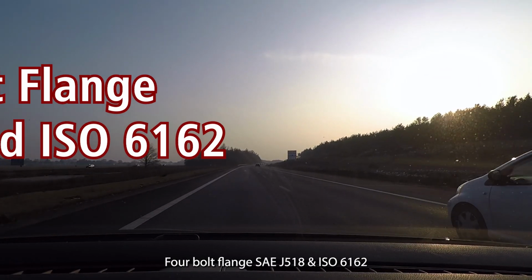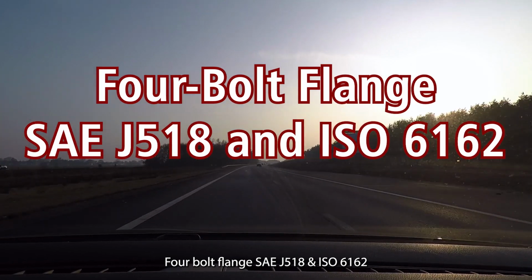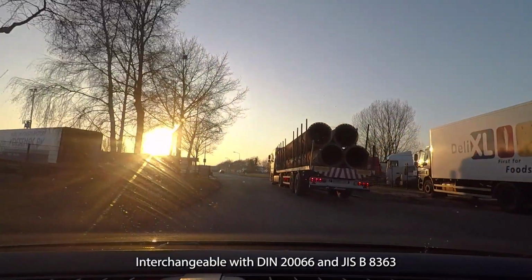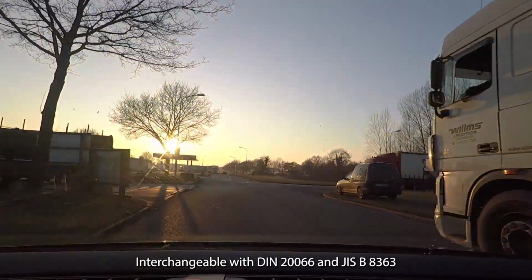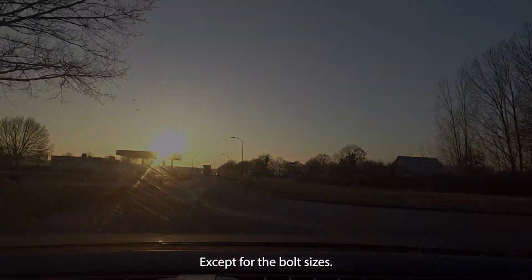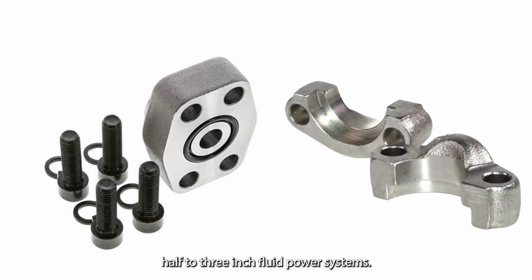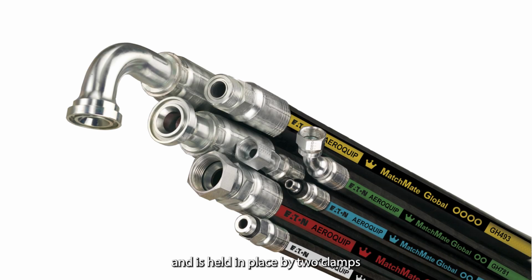4-Bolt Flange, SAE J518 and ISO 6162. Interchangeable with DIN 20066 and JIS B8363, except for the bolt sizes. This connection is commonly used worldwide to connect larger size hose and tubing, 1/2 to 3 inches, in fluid power systems. An O-ring, inserted into a ring groove in the flange head, seals on a smooth-faced female port, and is held in place by 2 clamp halves and 4 bolts in a rectangular pattern.